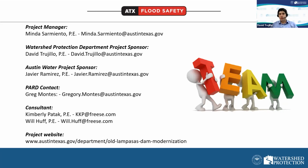So yeah, we considered removing the dam. However, even if we were to remove the dam, it would also require us excavating. TCEQ has very specific guidelines on how the dam needs to be removed, so it would still require substantial work. We would also probably need to do additional work downstream, because we would lose all the flood detention benefits from the dam. So in the end, it would be more disruptive if we were to remove the dam than fixing it. That's kind of what the results of the preliminary engineering report phase were.